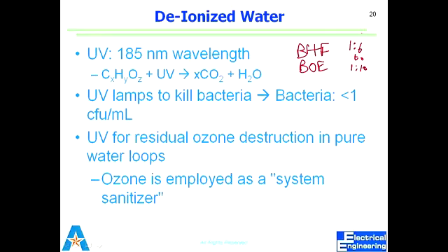So say if I dip my oxidized wafer into BHF, and I've timed it, so in 1 minute I'm done with how much etching I want to do, I take it out. How do I stop the reaction right here? Because some of the BHF is going to be on the wafer. Rinse. Put it in a beaker full of DI water. Rinsing will still not be consistent right away. But if I dip it in a beaker full of DI water, it's going to dilute the BHF right away. So I can pretty much control the reaction and stop it right away.